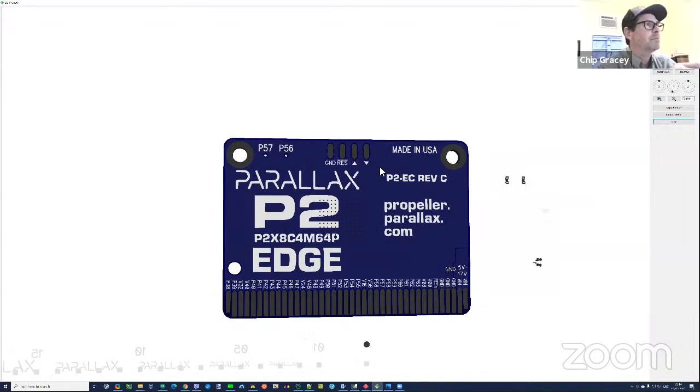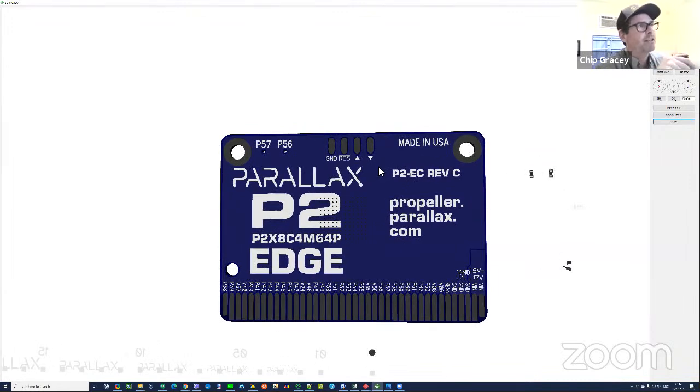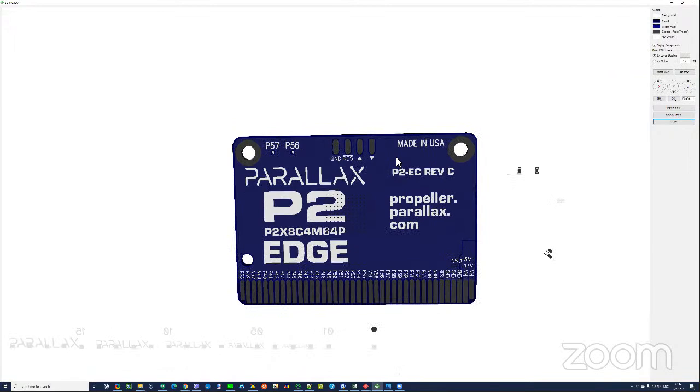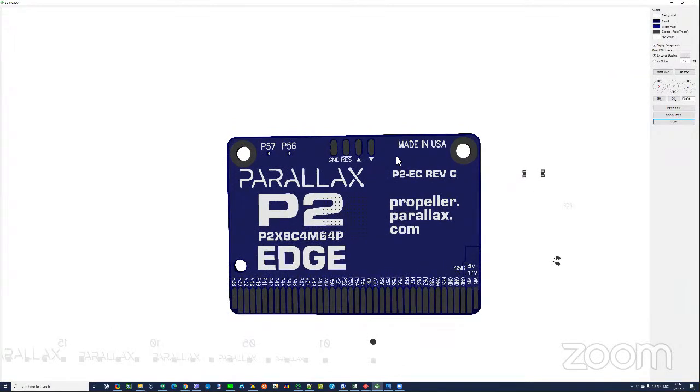It would be good also if you made a line right through the tool pads, that there was a full radius on the pad for the pogo pin, so it could be in line with the outer tool pins. I'll drop it down. It might already be there, just so the radius is fully there. I'm sure it's not there because I literally just dumped it there to show it now. I haven't aligned it at all, so it's just roughly in position. I think it will be aligned horizontally with the mounting holes, and then I suspect the silk will probably go on the board edge, not on that edge.